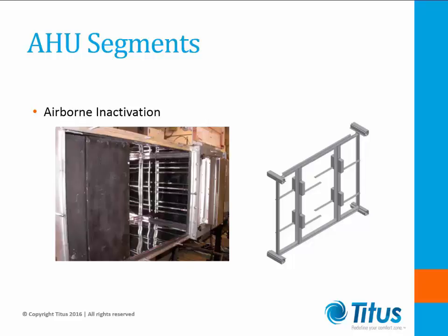A key aspect of this option is the fact that some pathogens may be too small to be trapped by the HEPA filters with 99.99% efficiency, but they are very susceptible to the effects of UV. The full air cleaning provided by this combination of HEPA filtration and airborne inactivation also achieves a disinfecting effect on local surfaces. Typical applications of this option are found in laboratories, food and beverage, cosmetics, or pharmaceutical industries.